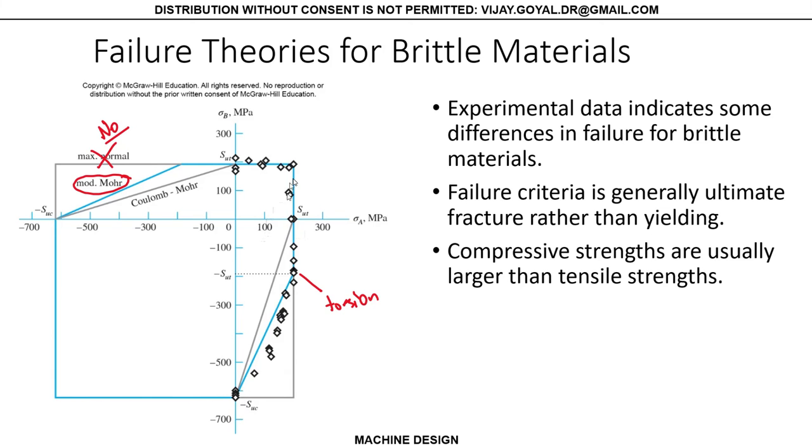And this applies the same as before. Let's suppose I had a load line here and I had several points, maybe a point A, point B, point C, and a point D. What can you say about those points? Well, you know that your point A will always be safe because it's inside the diagram.